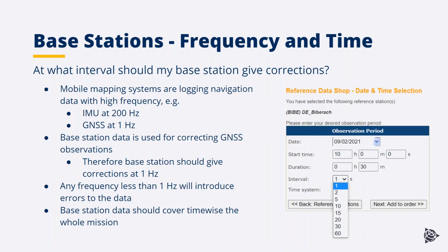If you are familiar with the Trimble Reference Data Shop, there's a menu where, when you order the data, you choose the interval. By default, that's usually 15 seconds. So you always have to remember to change that to 1 second data.